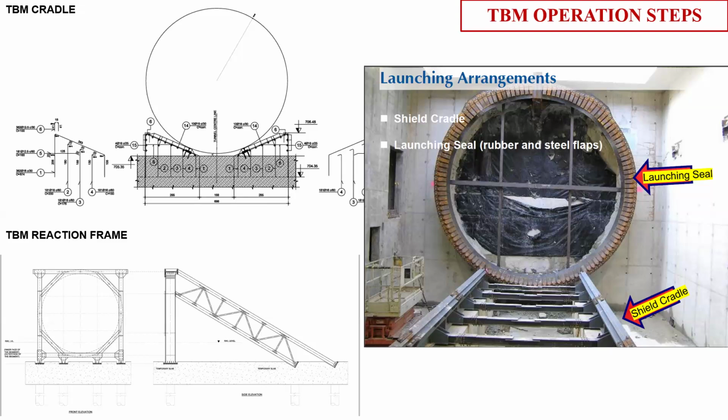I did not go into more details. I have seen the sealing ring here, even though there is no groundwater table in Riyadh. The water table is deep, around 50 meters below, but it still depends. It is not necessary that you need to put it. Basically, it's a gasket, the same gasket you use in the TBM segments, making a watertight structure.